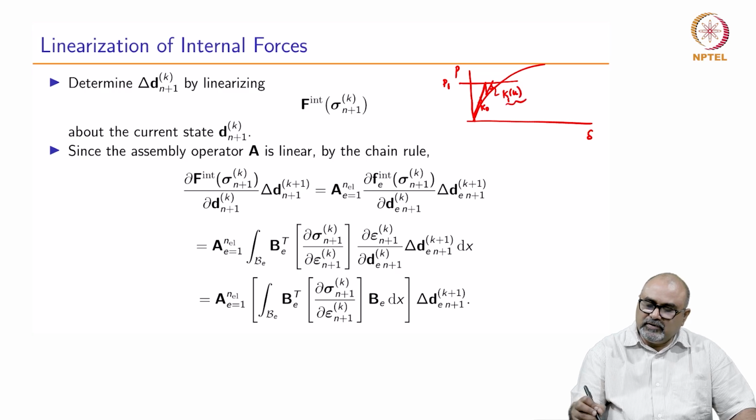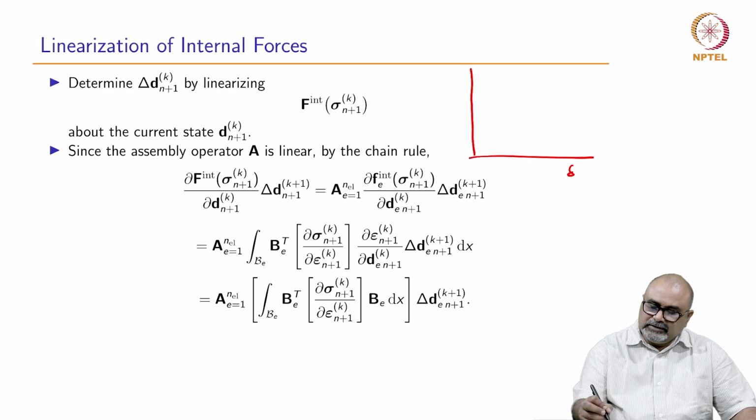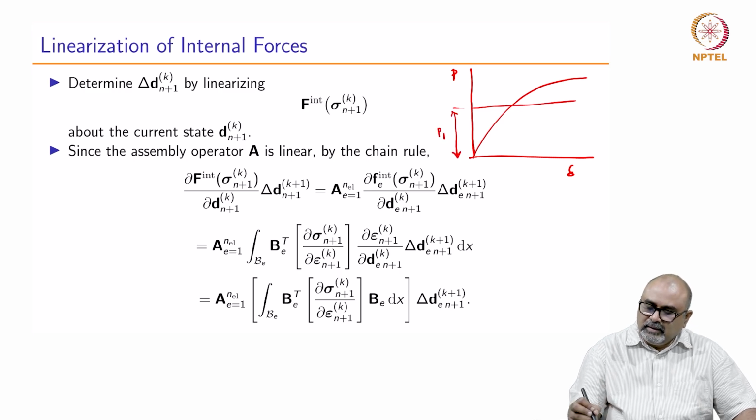So, this stiffness K1 of u at any value, let us say ua, at a point A. If we have a load deflection procedure like this, and this is the first step, which is P1, and we use the initial tangent K0 and try to converge, we get this point A, and the corresponding displacement is ua.